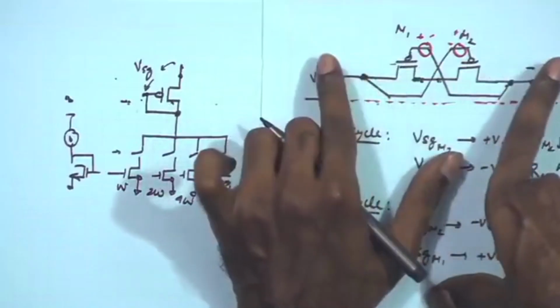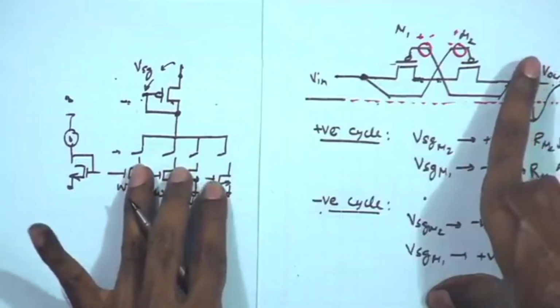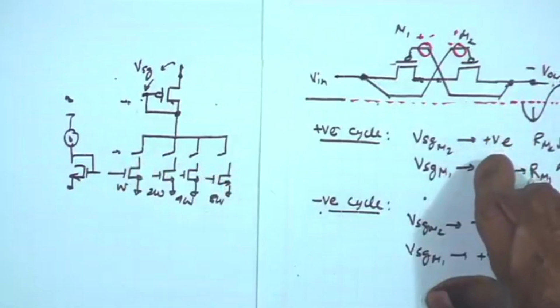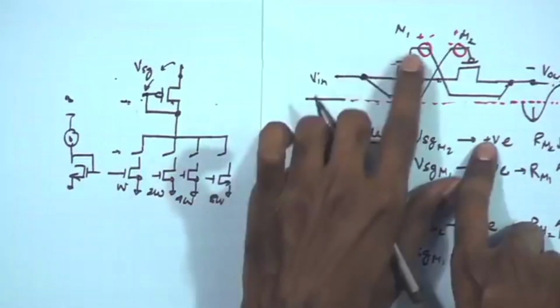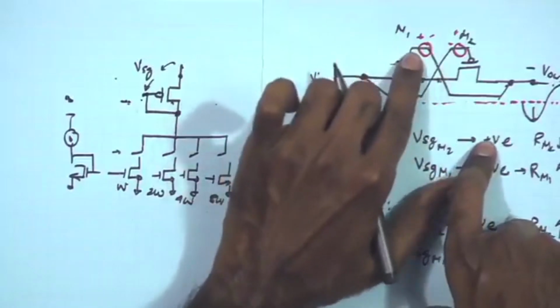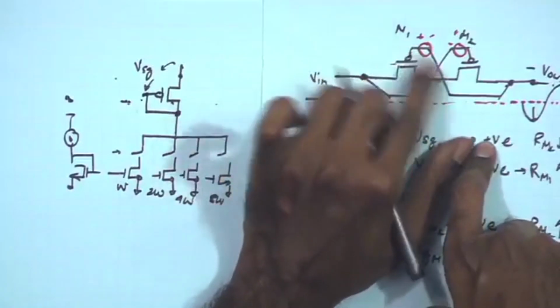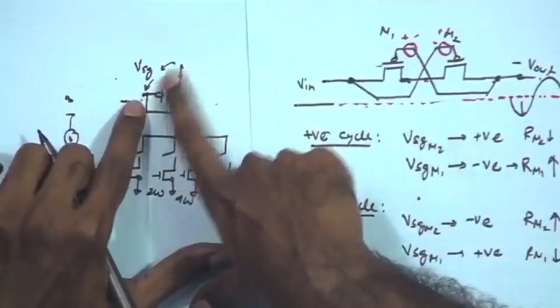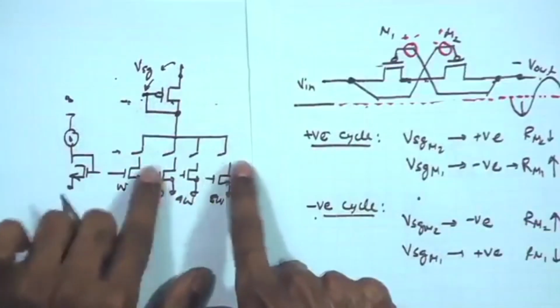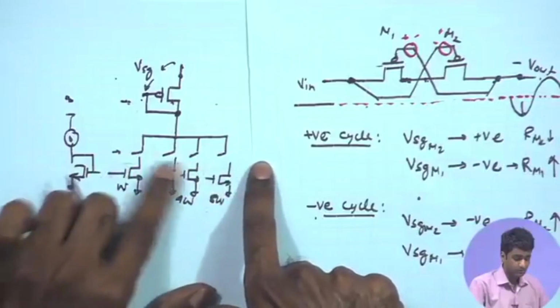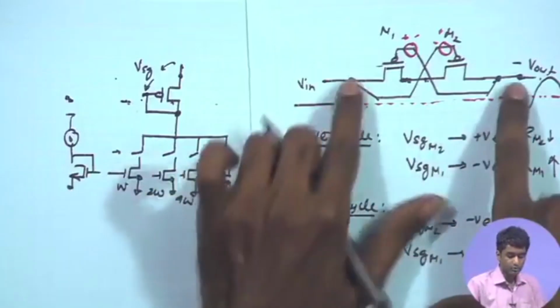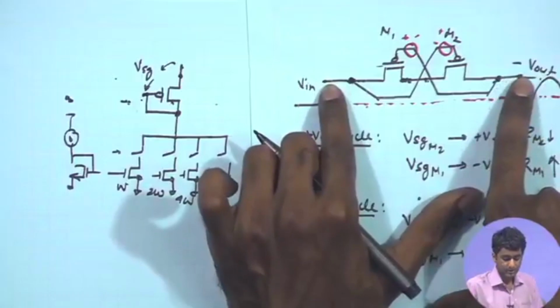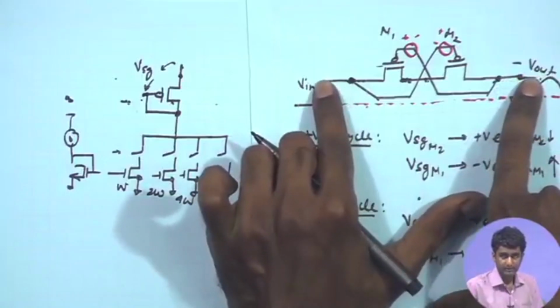You are going to have a linear range of resistance which you can tune by using the switches over there. So, this is one way in which you can insert an effective battery between these terminals and the gate, and hence control this battery by controlling this tuning options, these switches over here. This in turn controls the effective resistance coming between this V out and V in terminal.